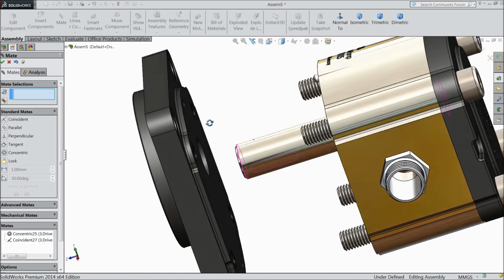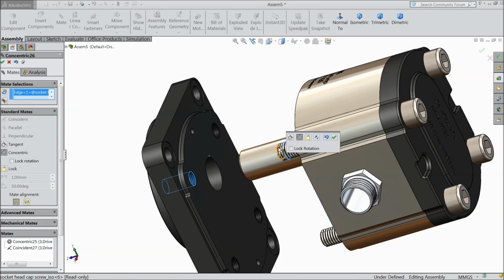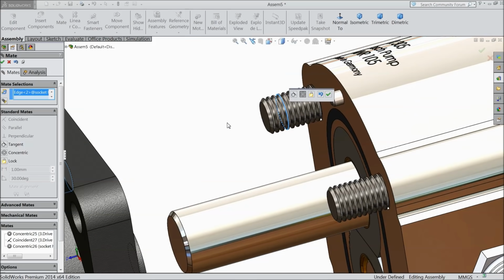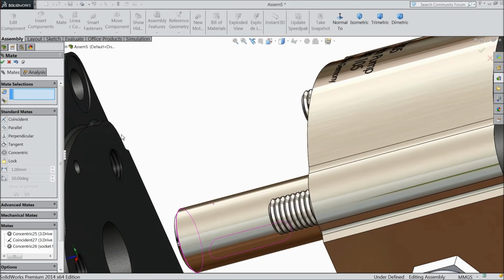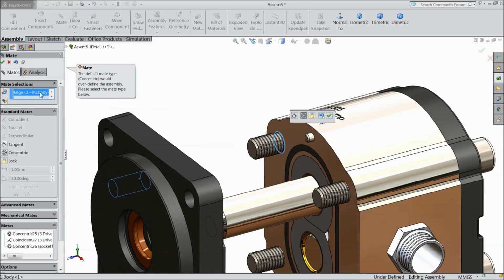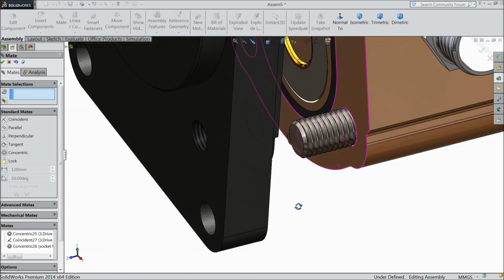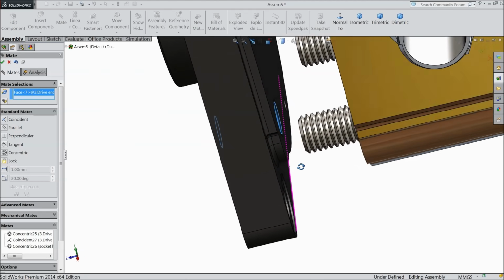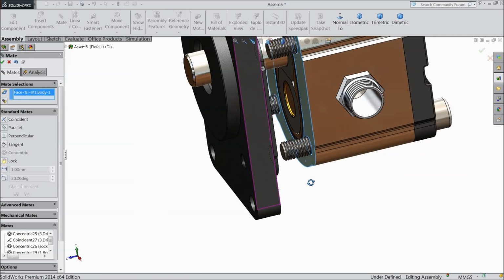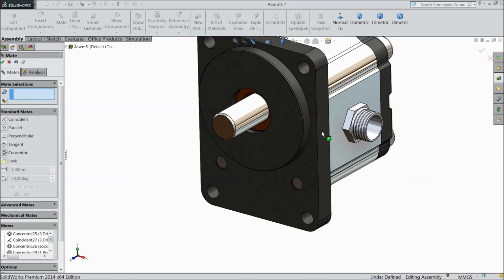Now these are the bolt. It should be fixed with this hole. Select this hole. Concentric relation. Or select this hole. Clear. Drag it this way. Concentric relation. Okay. Select this face and this face. Okay. Now see, our wall body is ready.